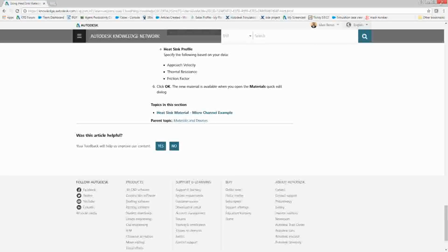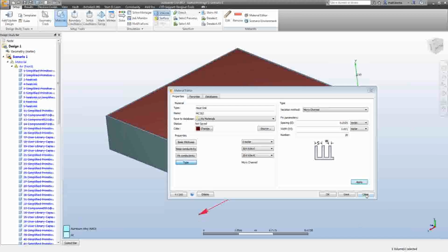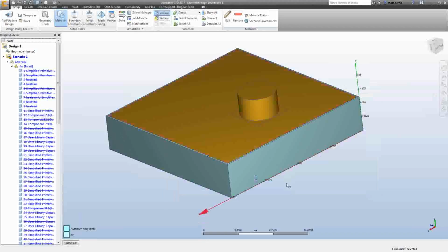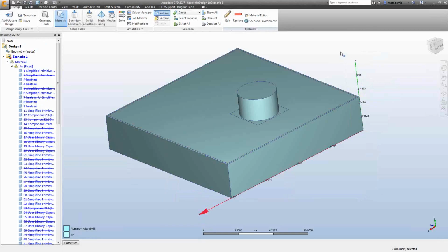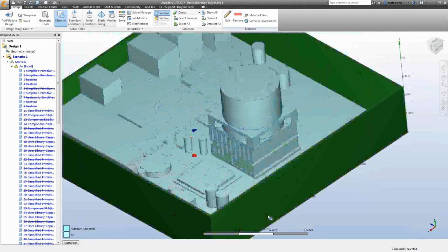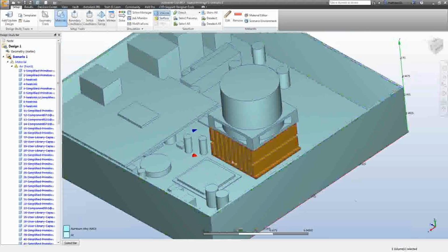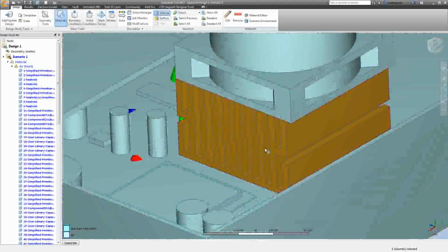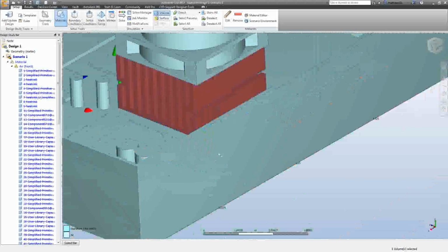So this will help explain. It's super useful. They will take into account the pressure drop on the flow through. So, like I said, you don't want to apply a heatsink material to our heatsink. You want to replace this volume with a box and then do it on that.